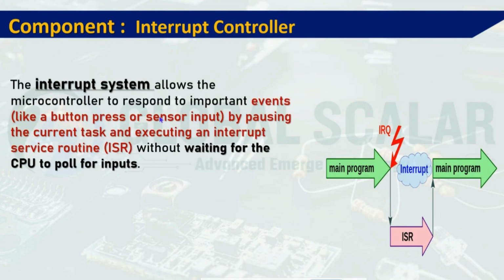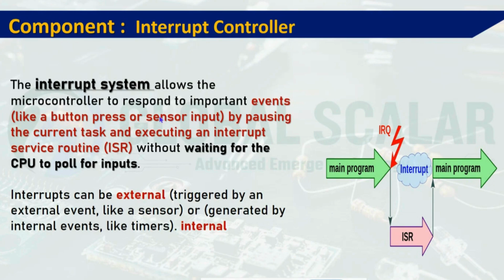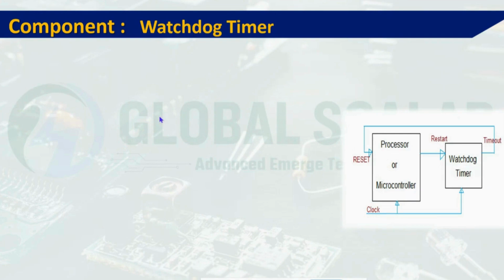So here the ISR is the interrupt service routine. It takes the responsibility to pull the data, whatever input we receive. So that will be decided. So interrupts can be externally triggered or internally generated. It depends upon the hardware and the complexity of the program.